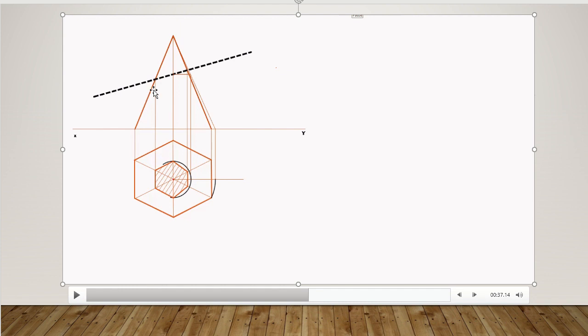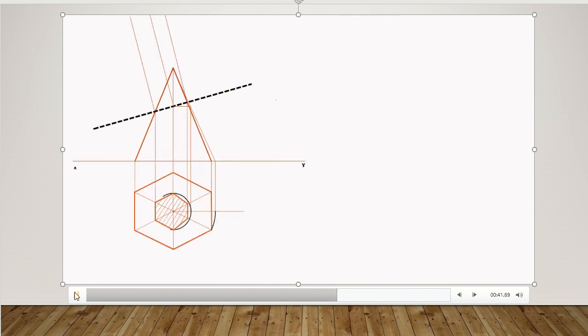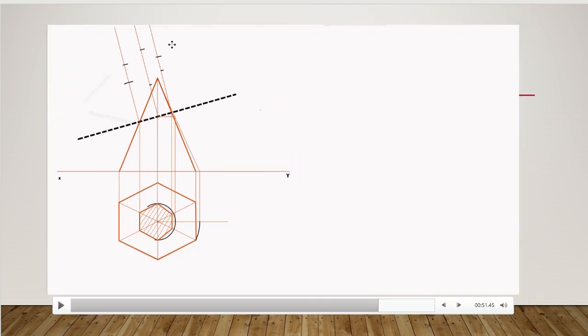Next step is, in order to draw the true shape, you have to project perpendiculars from these 3 points. Just check the next step. Perpendiculars are being dropped. Then measure this distance, that is, keep your compass needle here, measure this radius, and keep the same compass over here, then cut the same radius over here. That is, you are transferring all these points by measuring from the XY reference line onto this portion. After transferring all the points, you join them, after which you need to hatch it.